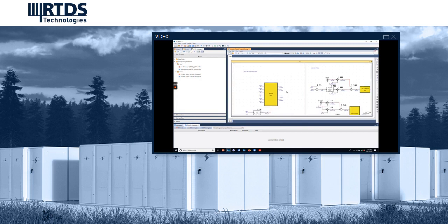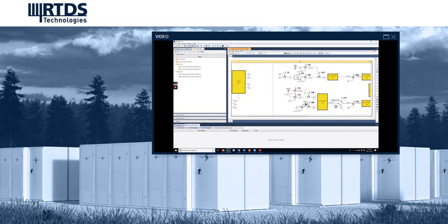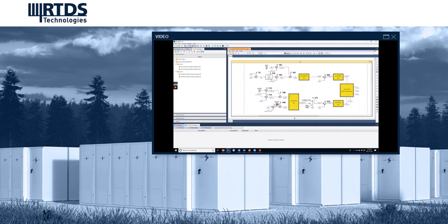The grid side control uses the grid voltage orientation, where the D-axis current controls the DC bus voltage and the Q-axis current regulates the reactive power. The grid side D-axis current can be set to control the reactive power by regulating the grid bus voltage, or set to 0 to minimize the grid side AC currents.